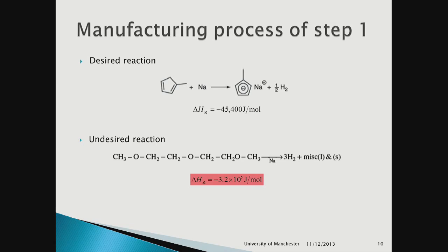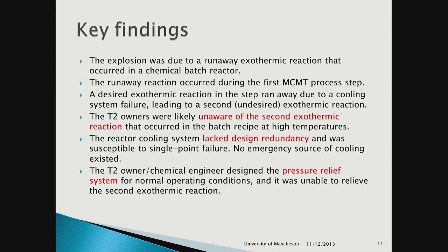The moment the water didn't go off, what they didn't realize was the moment they got to this temperature, that reaction kicked in. They legislated for only the top reaction, and they would never ever go faster than this, and this is the vent rate, and they'd done all the stats, but what they didn't realize was they had a bomb, because this reaction has 8 times more energy released from it, and of course it therefore heated everything up in a split second, and it went bang.